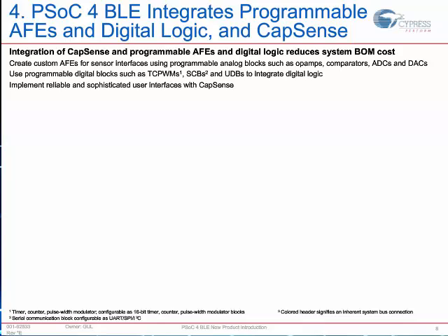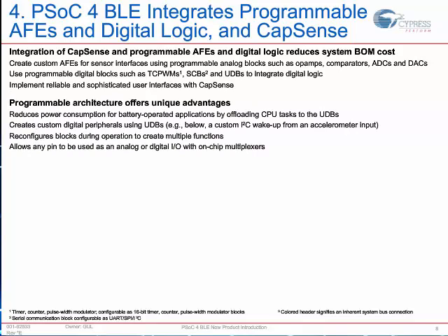So at the end of the day, what you get is a very tightly packed, highly integrated system that offers a microcontroller, which is an ARM Cortex M0 core at 48 megahertz, a Bluetooth low energy radio inside the chip with an integrated balun, a whole lot of analog components like an ADC, op-amps, comparators, and muxes to create analog circuits that eventually act as your sensor interfaces, and another set of digital fabric that allows you to create any sort of other custom peripherals or control systems, all integrated inside a single chip. And all of these are programmable over and over again.